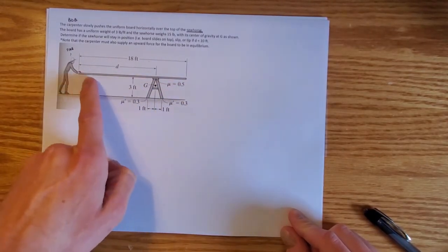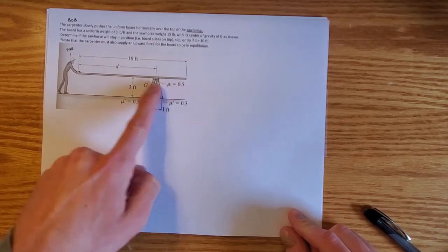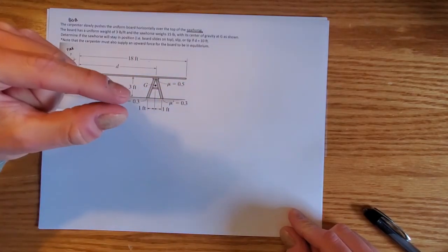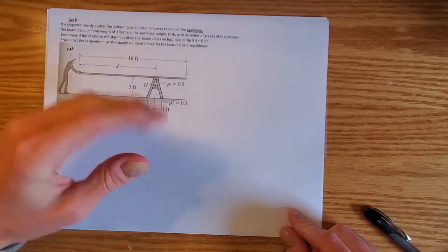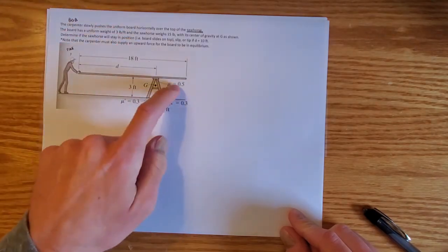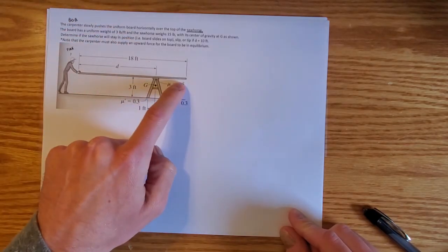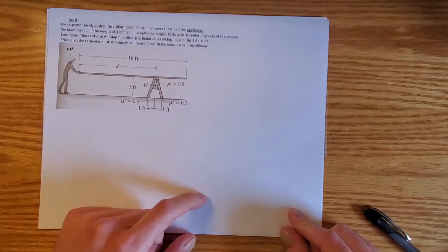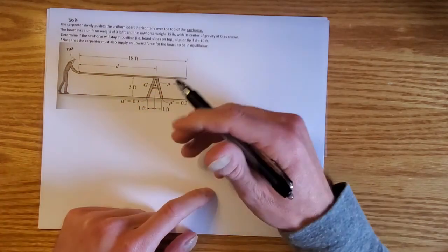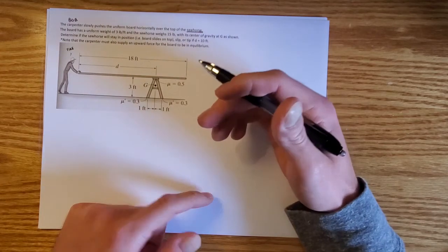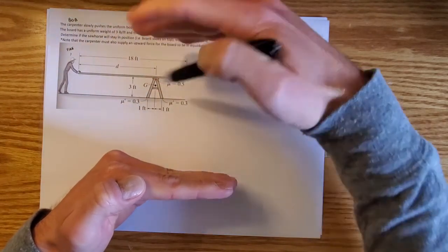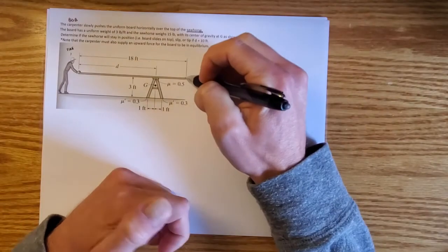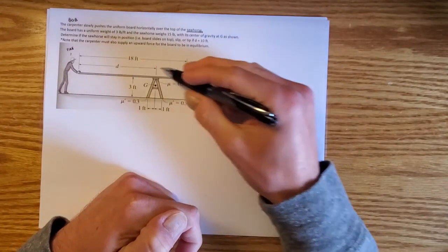But something you can notice is that we don't have a height for the board. We're assuming that the board is super small, probably about 1 inch or so, so it's not going to be able to tip as a result of not having any height. Remember that our equation for tipping involves how high we're applying the force relative to the object to cause it to rotate. So anyway, the only thing that this board can do is slide.